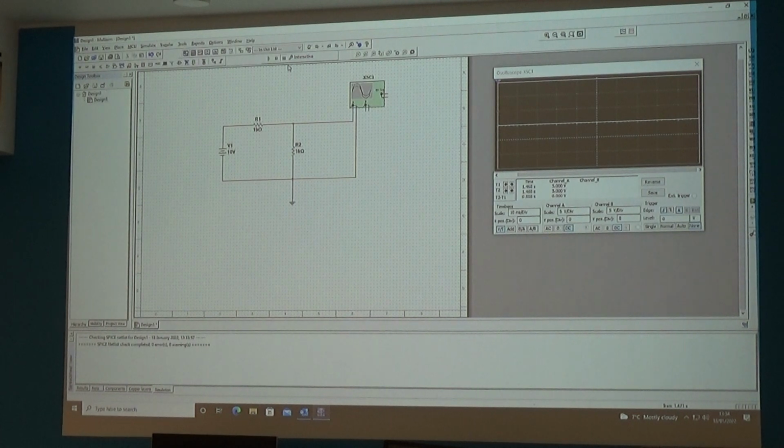Good stuff, right? So you now know how to get hold of components, you know how to pull components into the drawing area, you know how to perform measurements with virtual tools, so multimeters, oscilloscopes, these kind of things, and you know how to run a simulation, which is to press this magic button here. Now you must remember to stop the simulation once it's running, because otherwise it'll affect other things which are inside models.